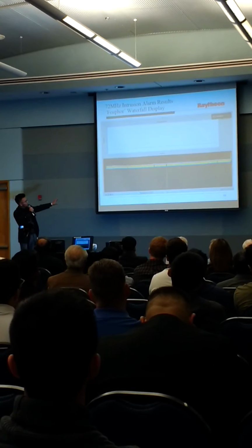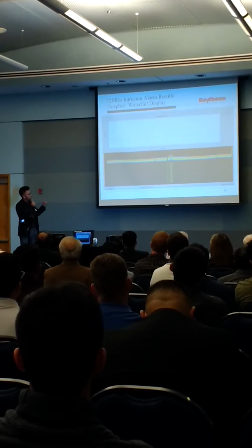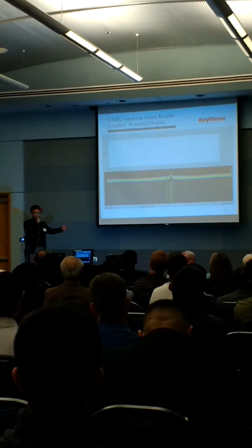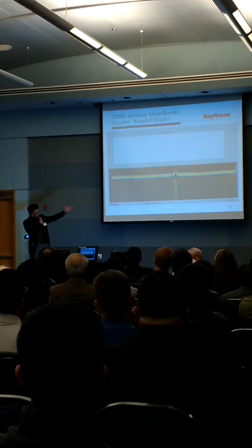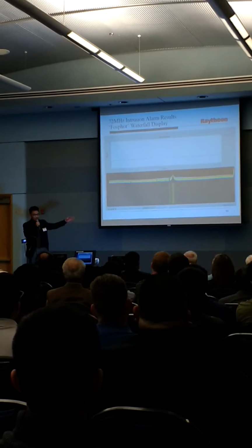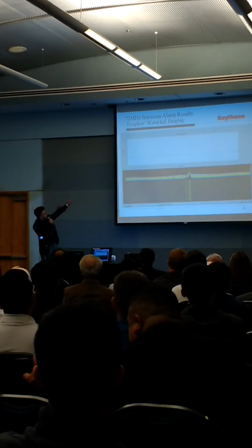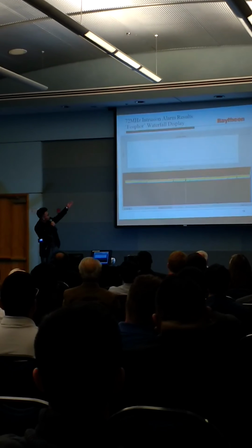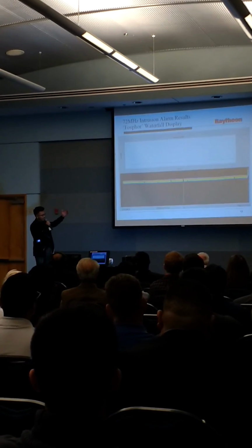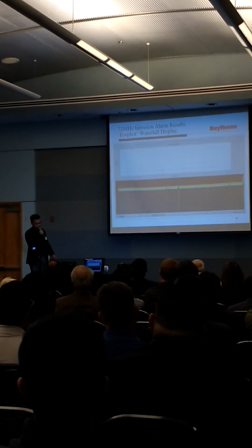So when we turn on the 72 megahertz source, we can see that the audible alarm is being triggered, and that the waterfall display is now showing us the constant transmission. We could also note on the top that it's constantly outputting a 1 when the intrusion was detected. But now it's off, so the system returns to 0.